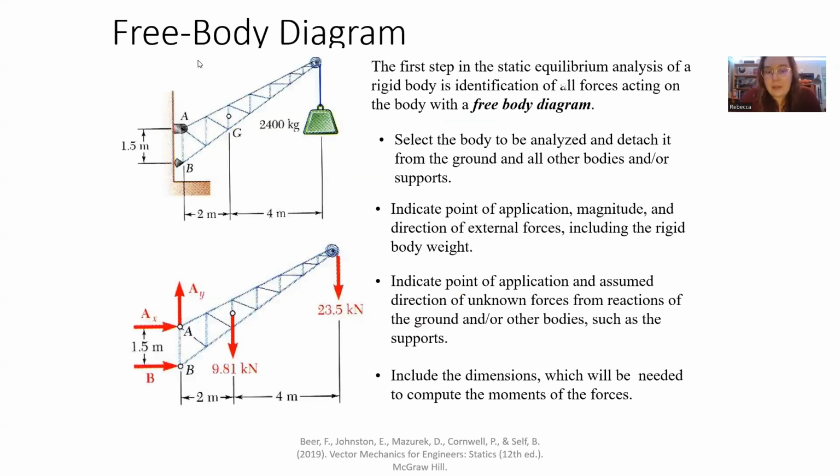So again, looking back at this example, let's specify our boundaries. Let's figure out what we want to be the boundary of our analysis. And anywhere we make a cut, we introduce a force. So we have our force from this wire, two forces from our pin, and one force from the rocker.